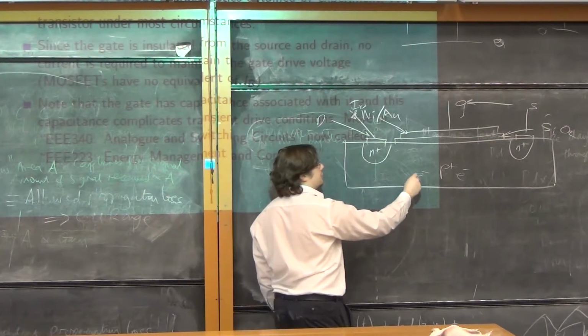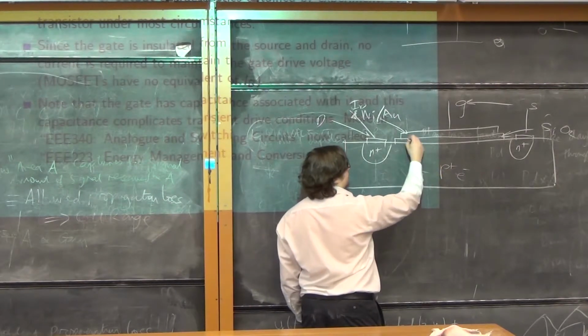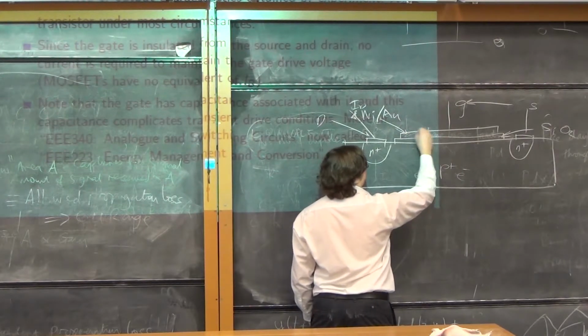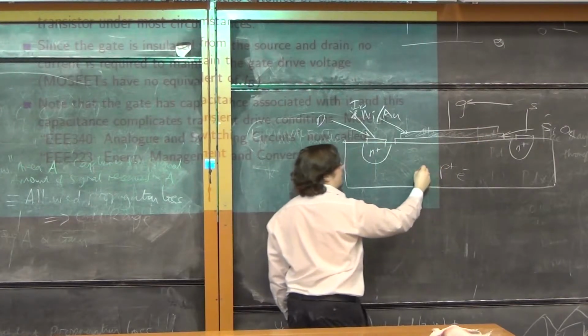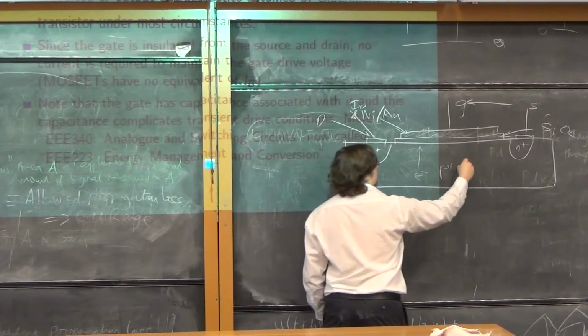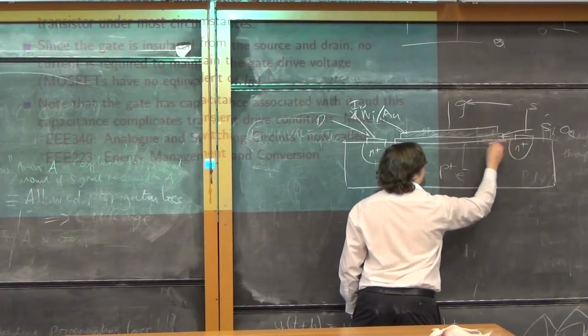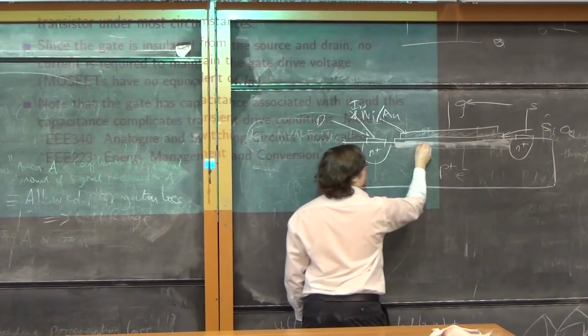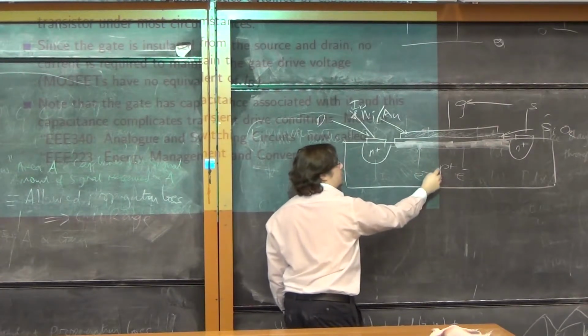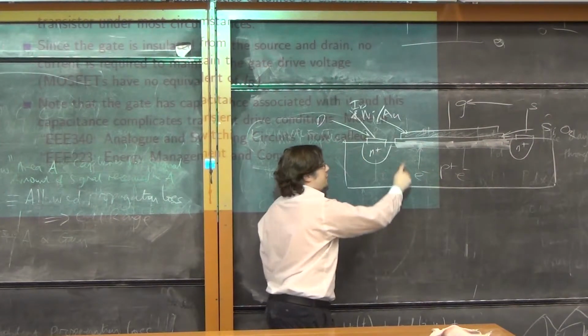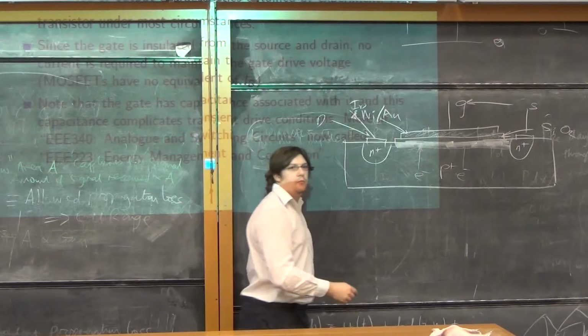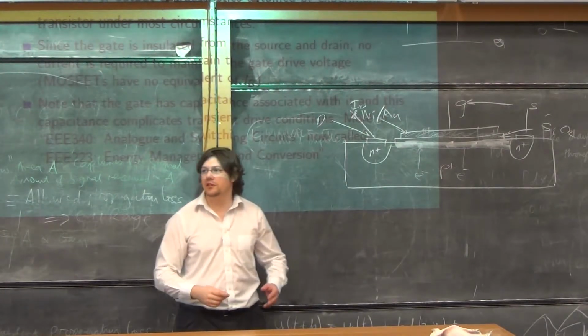What we really want to do, using a potential on the gate electrode, is to attract electrons up here until we've got enough of them in a region that this P+ material looks in this specific bit more like N+ material because there's a high concentration of electrons.